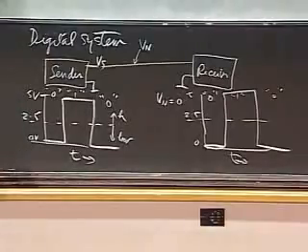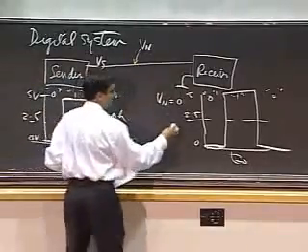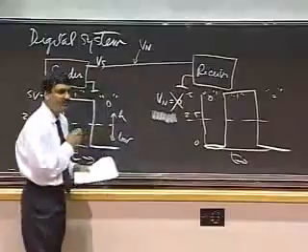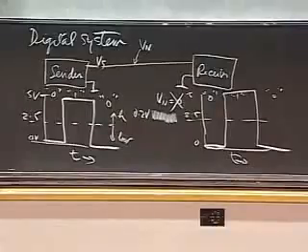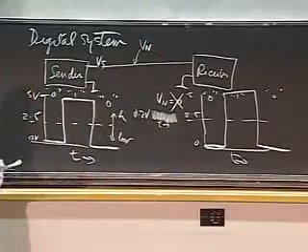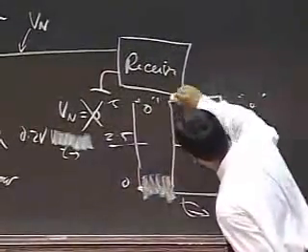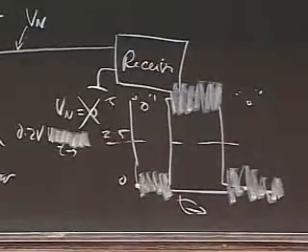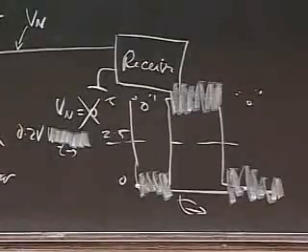Now, the beauty of this is that suppose I were to impose noise, much like I had noise out there, and Vn was not 0, rather Vn was some noise voltage, let's say 0.2 volts peak to peak. Let's say that simply got superposed on the signal, in which case what do I get? What I end up with is a signal that looks like this. The receiver gets that signal, because the noise is added into my signal, and that's what I get.